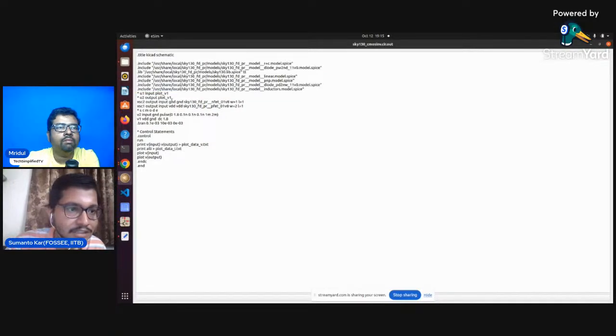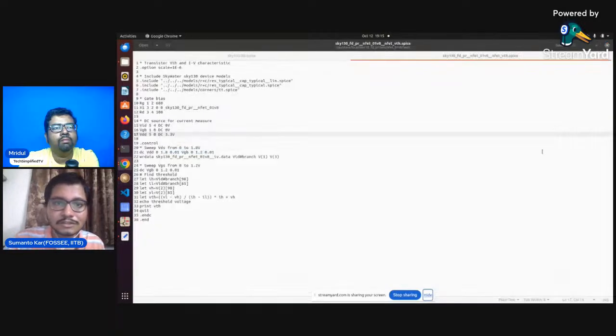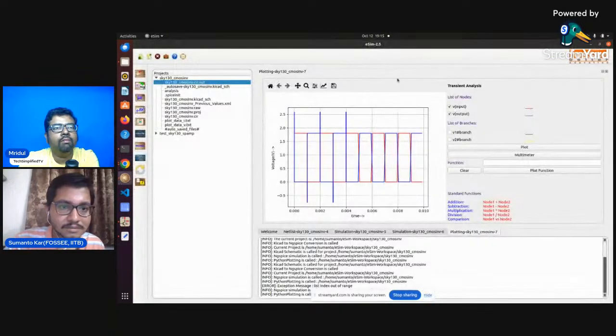XSC is the sub-circuit name made for the SKY130 models. So the NFET model, and the width and the length have been specified here. Whatever we passed as the input, the pulse source, DC source, transient, and so on, printing the values and current and different other things. Yes, so this was all about the waveform and simulation of the inverter circuit.